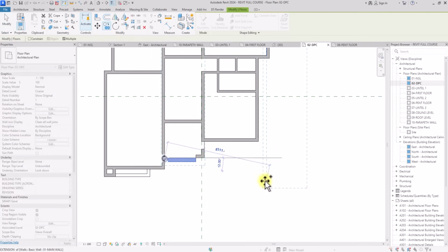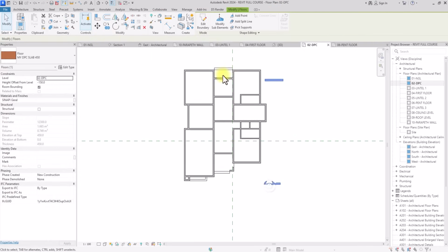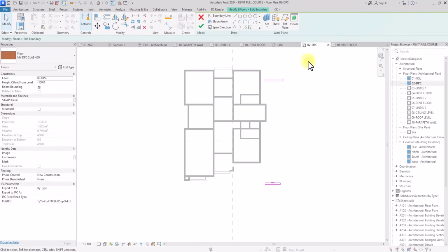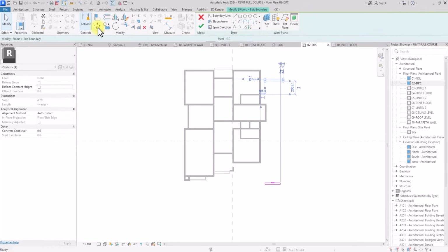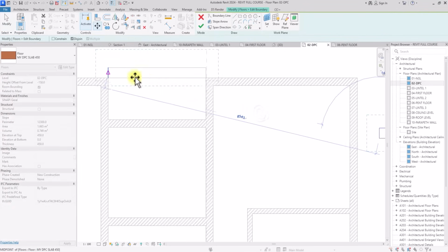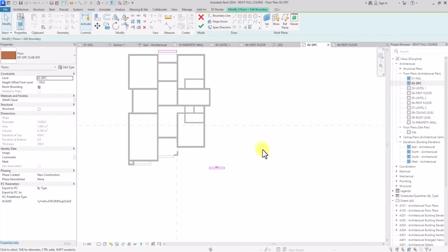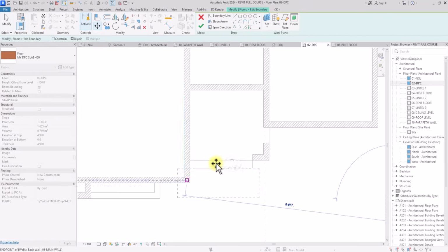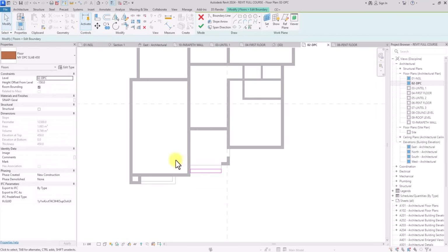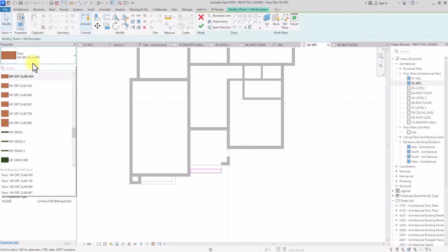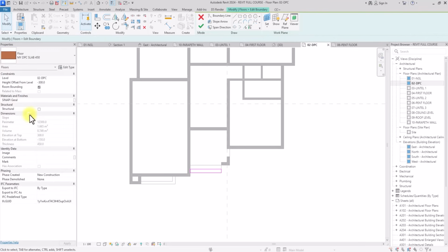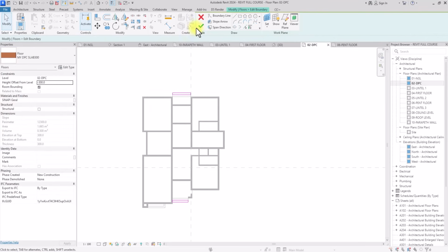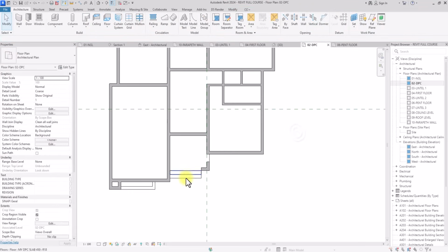So now I've done this, I'm also going to copy this floor off. I'm going to click on this and I'm going to edit the profile. So I'm just going to select this profile, and I'm just going to move it and place it after this one to create another step profile. I'm going to do the same here and just move it to this point here. So now I've moved it, I'm going to change this to -300. Then I'm going to change this floor slab to 300mm thick slab, so it will just be adjusted. So as you can see, we've created this next step.